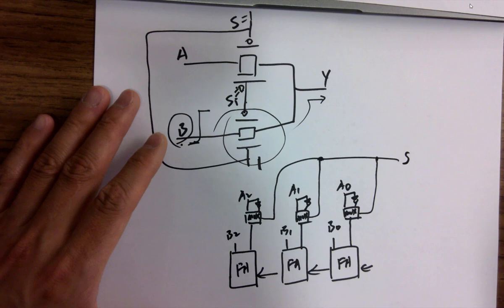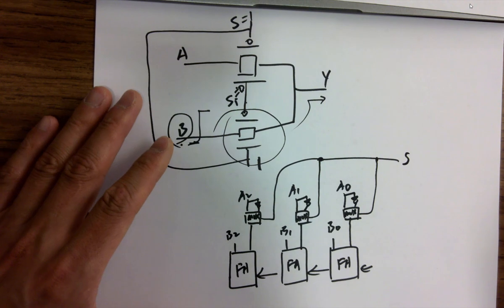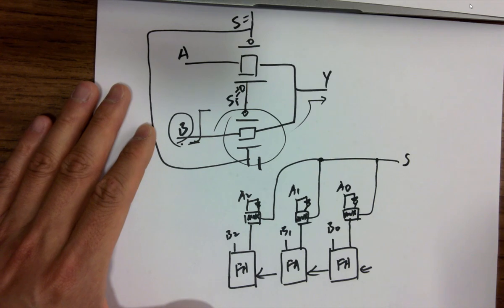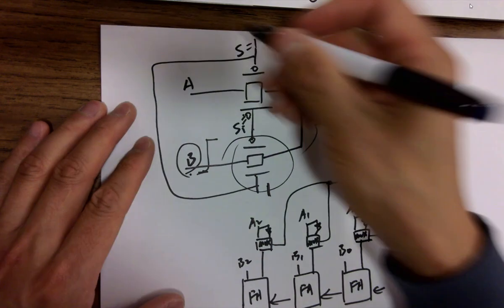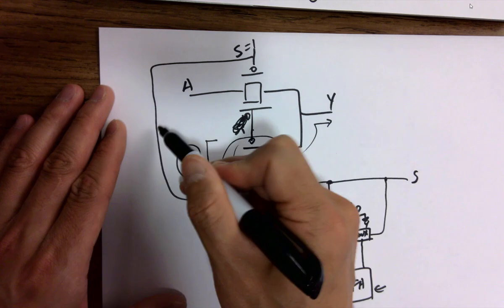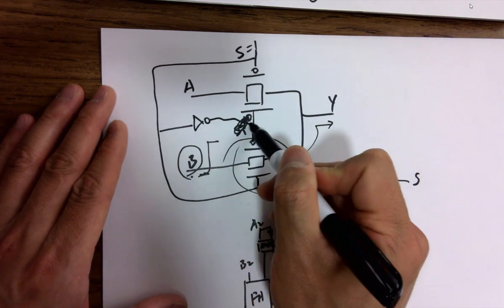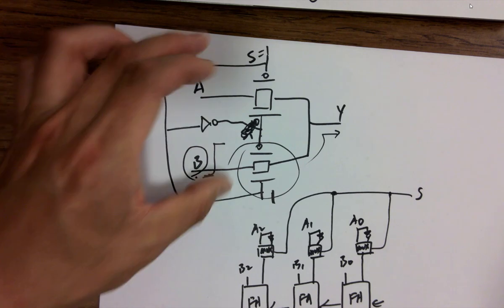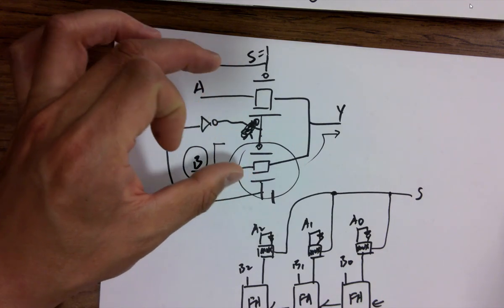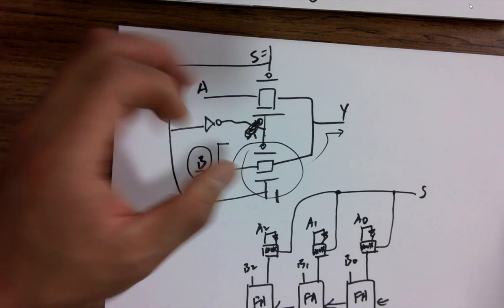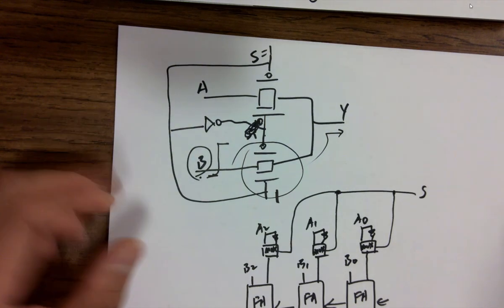So that's S. You just need one selection bit because for this selection pin, you're basically just adding an inverter and sending it to the other line here, right? The 2 to 1, you only need one selection bit because you only need two different options, 0 and 1, right? Same here.